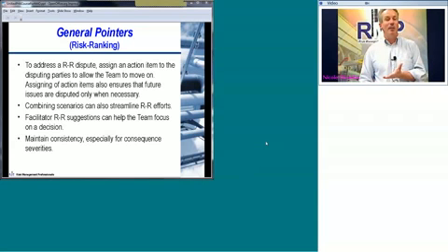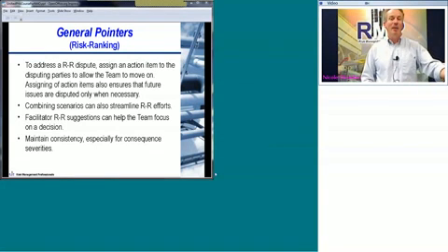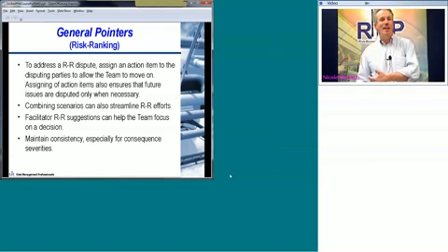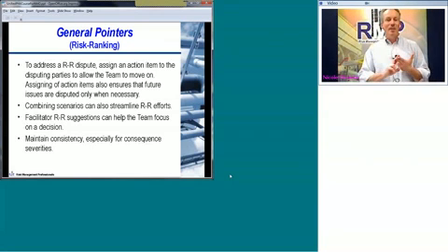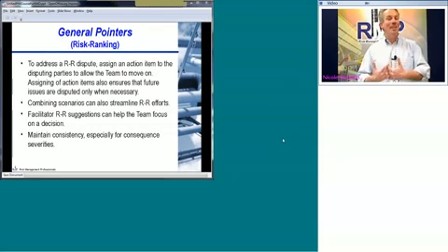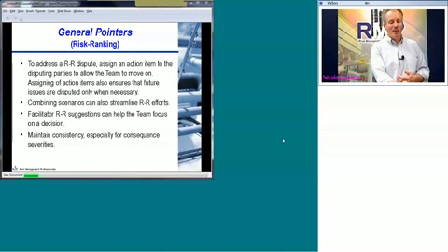If you've got one scenario that is an overpressure of a vessel and the team ranked it as a severity B, and then 15 minutes later the same vessel overpressurization is ranked as a severity D, there's an inconsistency problem. Either they didn't understand, or perhaps they're thinking of a different scenario and we didn't quite capture all the right details in the HAZOP study. Either way, that's something you want to resolve, and the risk ranking helps you do that.